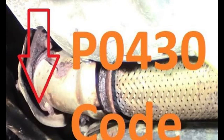There are a few ways to test an oxygen sensor for a P0420 code. One way is to use a code reader or scanner to check the oxygen sensor readings. Another way is to use a multimeter to measure the voltage output of the oxygen sensor. If you are experiencing the P0420 fault code, it is important to have it diagnosed by a qualified mechanic. They will be able to determine the cause of the code and recommend the appropriate repairs.